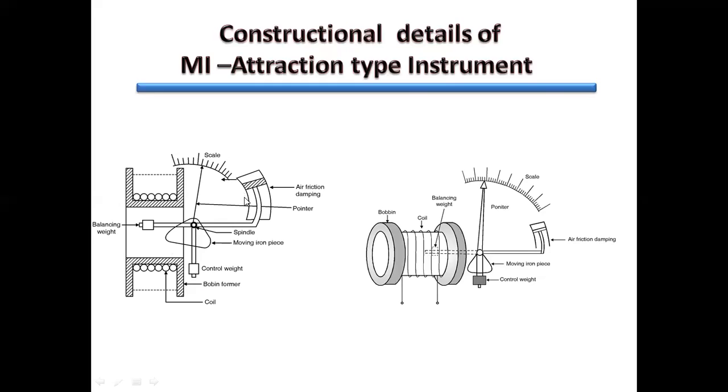We have got an air cylinder here. The piston is arranged inside it. The rod is connected to the spindle. This chamber is closed from both sides. So whatever air is trapped inside this cylinder cannot come out. The moment this rod moves up and down, the piston movement in these two directions occurs.